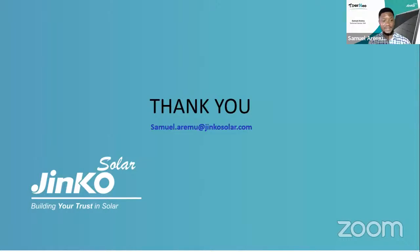Okay, like I said, there's one factor I mentioned, which is the days of autonomy. You can say 2 days, 3 days, but that is going to increase your cost. And when we are sizing our PV modules, we use the worst case scenario. That means the worst temperature conditions during winter. The peak sun hour is 4 hours, but actually you have more than 4 hours of sunlight in a day. So we've sized the PV for the worst case scenario, that means during winter or during the rainy season. To cover this, you can also expand your battery capacity, which is based on the days of autonomy.